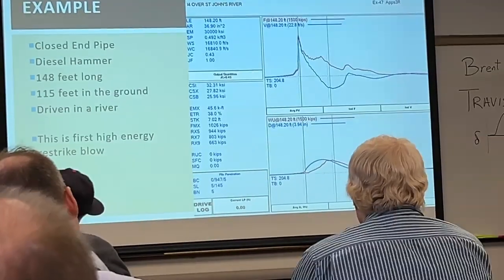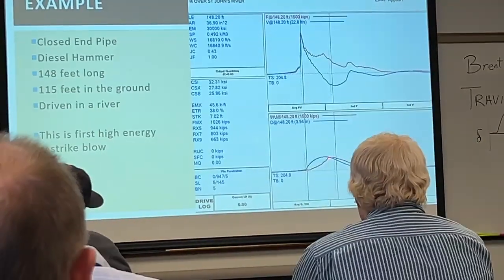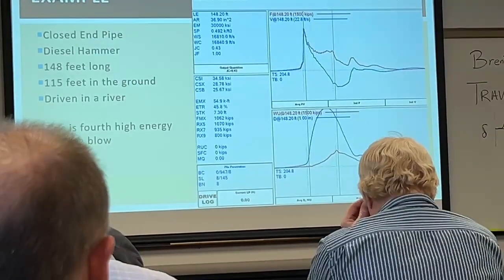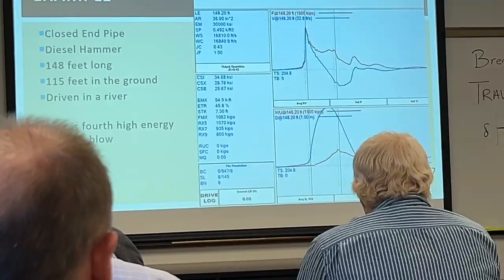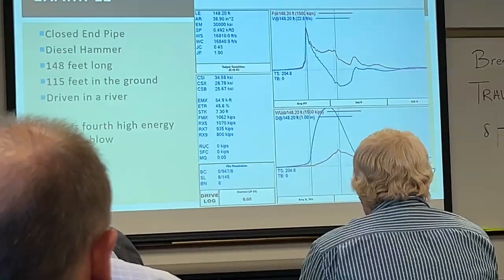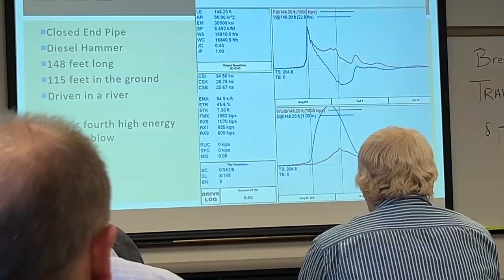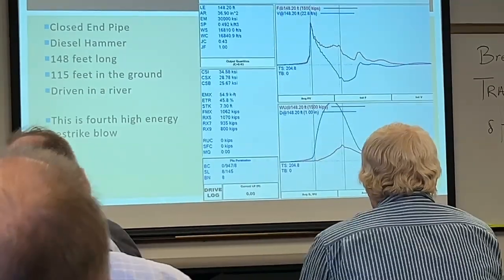And what we can see is, this red wave up curve has now jumped up some more. So what happened? We've actually started to, we got more energy into the pile, more force into the pile, and now we're starting to move that lower bit of the pile.